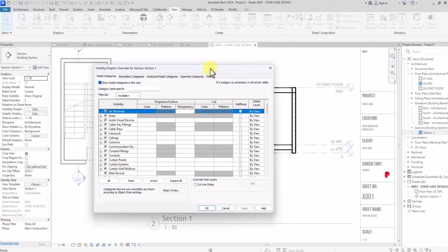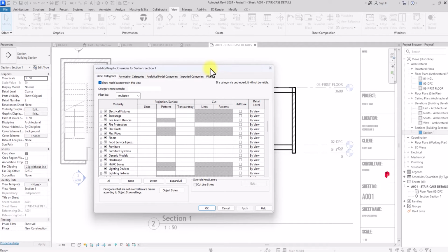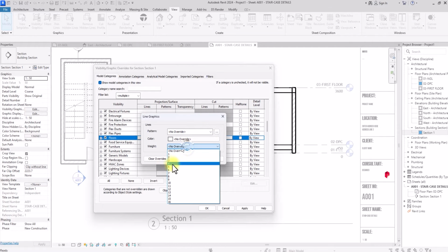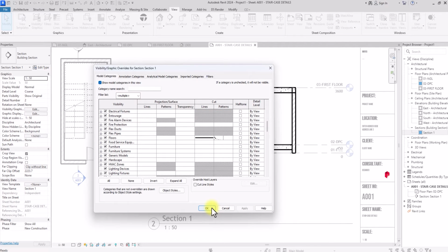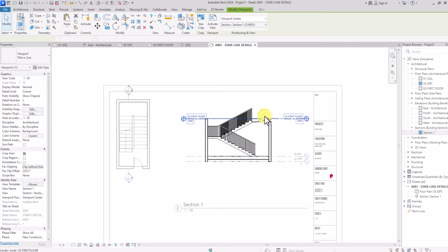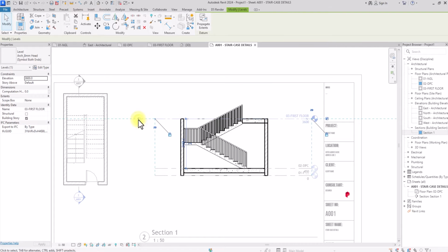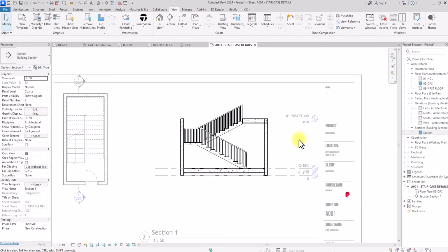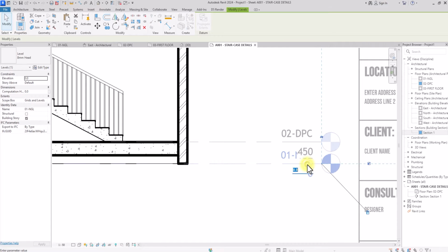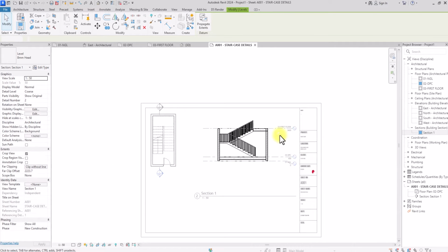So we're just going to go to floors. Then under these floors, we're going to go to override pattern. Then we're just going to look for a concrete material, click on it, click apply, and override the thickness, making the thickness the same as the walls. So now we have done some basic settings. We could just click on this again, click on this level, and we're just going to uncheck this second level head, so everything will be unified. We're going to click on this zigzag icon to just drop down this level so it will not be interfering graphically. Okay, so now this is done.